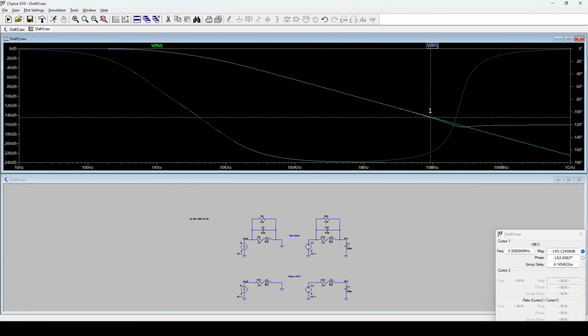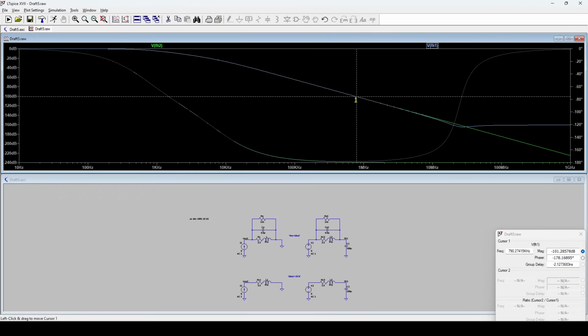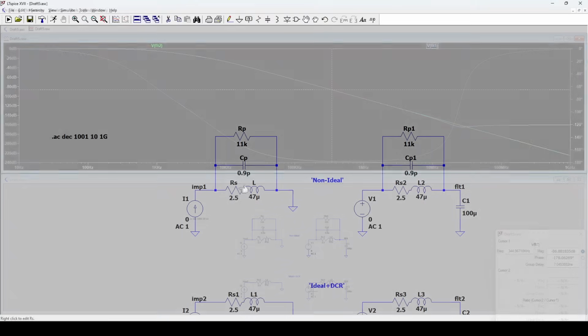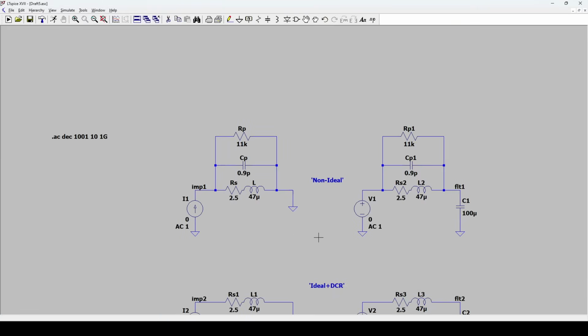Below or away from this self-resonant frequency towards DC, these filter models are quite similar. So this is a model you might want to use if you're running RF simulations. You might want to include even more information, more detailed capacitances and inductances to model the situation more appropriately. Whereas for a buck converter simulation where you're running at a switching frequency of, let's say, 500 kilohertz, the DC resistance plus inductance model might be completely appropriate. I'd like to add a couple more words to SPICE simulation, however.